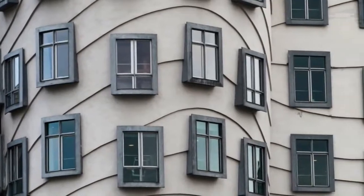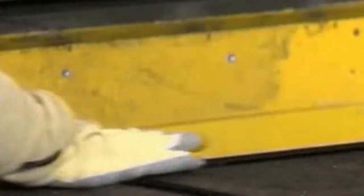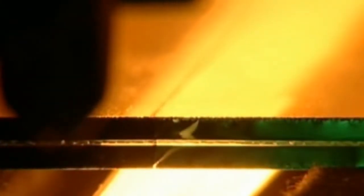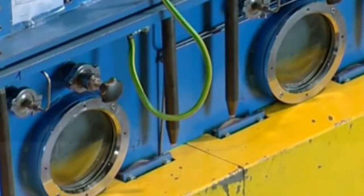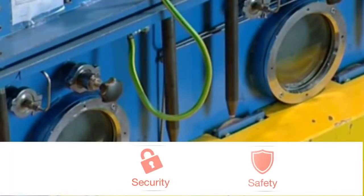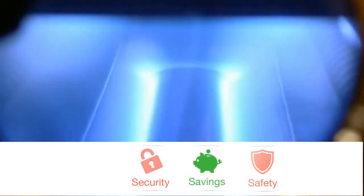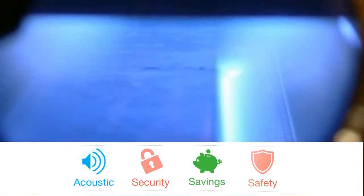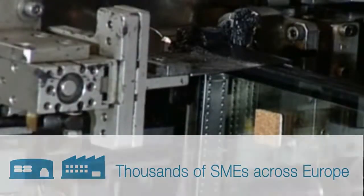Before being used in windows, windscreens, or any other application, these pieces of glass will be further processed. Depending on final usage, they will be cut but also tempered or laminated to give them safety characteristics. Coatings will be applied to them to enhance their energy performance, and they will be assembled into double or triple glazed units. These processing activities usually take place on separate manufacturing sites operated by thousands of SMEs all across Europe.